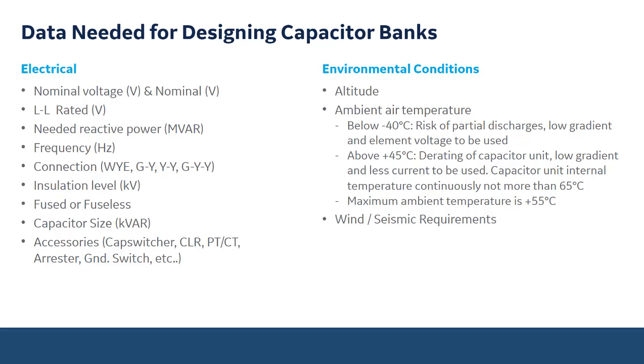The dielectric oil in the capacitor is still viscous, and so where you actually have more difficulty is when you run capacitors in very cold ambient temperatures. And at that point, what happens is your dielectric fluid can start to become less viscous and has trouble with the operation at that point.